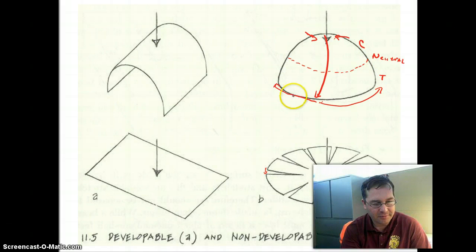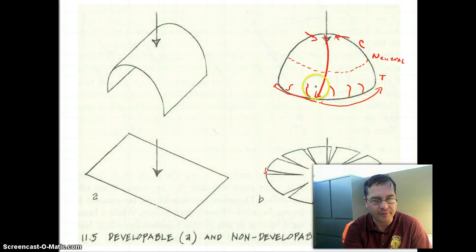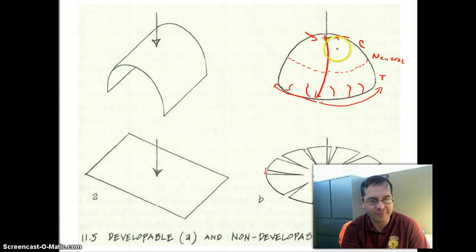So in domes of antiquity, one of the things that we've seen over the years is that these domes develop these tensile cracks at the base, and then they have to do some type of attempt at a repair, like belt it with a large chain or something of that type. Above, they're in compression. Now, domes of antiquity were made of materials that were strong in compression, and so we don't tend to see, for instance, the tops of those domes failing. They're quite robust to that.